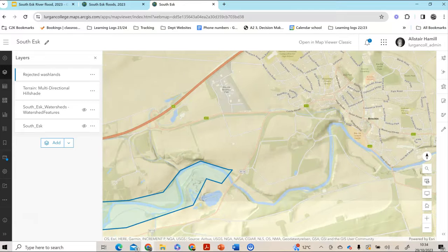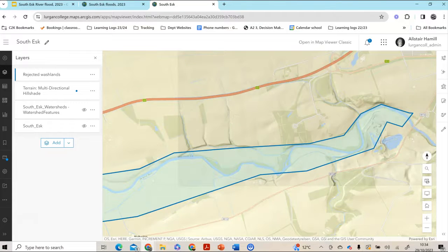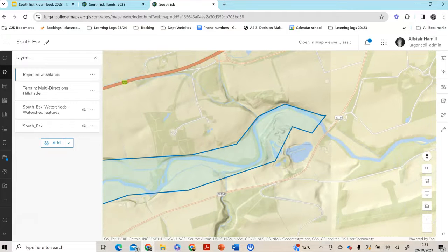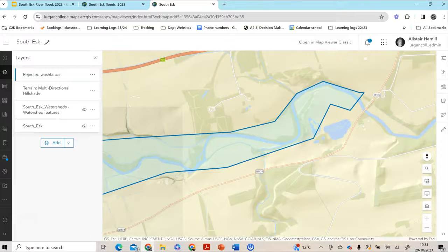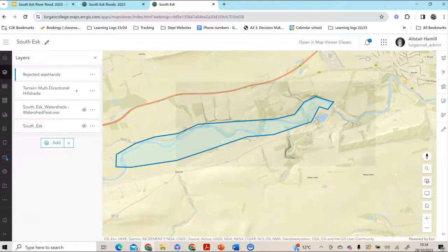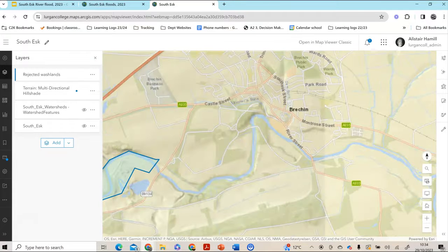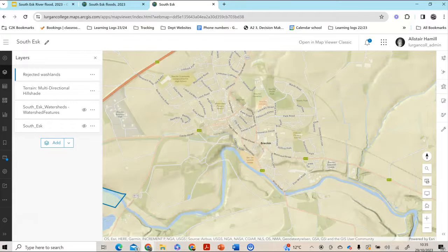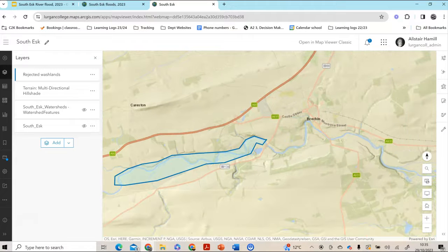And this area, this just upstream, was being proposed as a natural store. They were basically going to put a sluice gate on there, which would have partially closed, allowing the flood water to build up here rather than just heading further downstream. So the idea is that the water as it's coming downstream is stored here rather than coming down and flowing into the town down around about here. That's a very classic soft engineering strategy, and as you see from that paper that we just looked at, they rejected that on economic and indeed environmental costs.